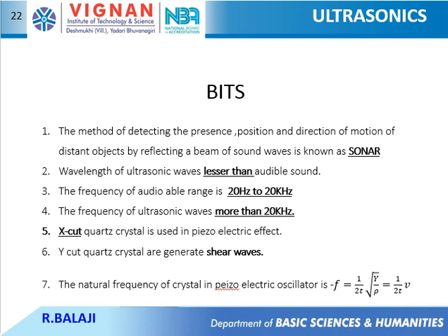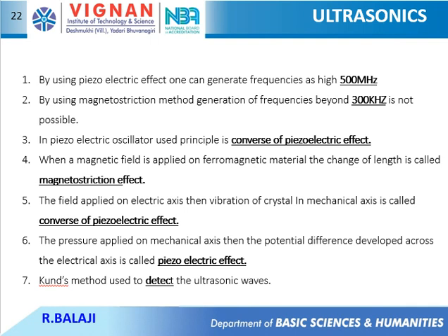In the piezoelectric effect, we use X-cut quartz crystal. Y-cut quartz crystals generate shear waves. The natural frequency of a piezoelectric oscillator is f = (1/2t)√(Y/ρ), where t is the thickness of the quartz crystal, Y is Young's modulus, and ρ is the density of the quartz crystal.